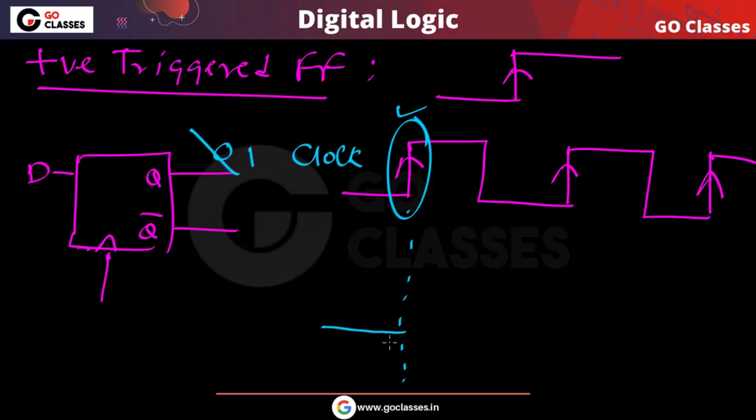If you want to change your output Q from 0 to 1 during this rising edge, then what I need to do is apply the input D sometime earlier, sometime before this rising edge. Because I have to make this input D equal to 1, I have to apply D equal to 1 at least sometime before this rising edge.